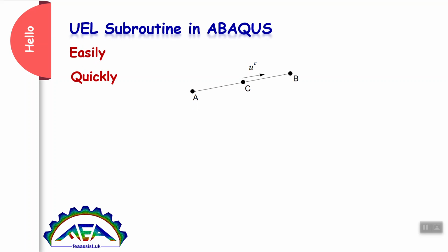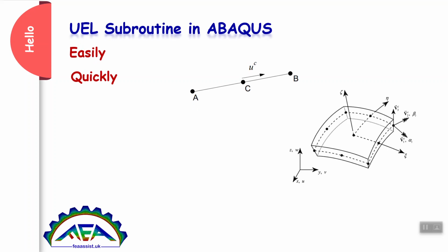Interpolation function can be linear or cubic. You need to define your function in the UEL subroutine. For 2 and 3 dimensional problems, it's the same. We need to define a new element with a new interpolation function. To understand these things well, stay with us.